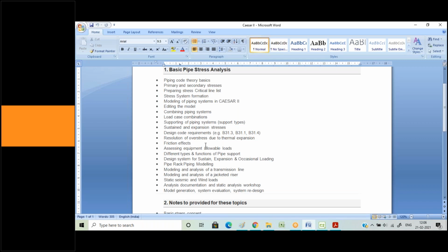Now when you're importing that particular load, if you have messed it up, X goes into Y, Y goes into Z, and Z goes into I don't know what, then that entire analysis comes to zero. So you have to actually understand the axes correctly: what has to be the axial axis of the line, what has to be the tangential axis of the line, and you have to emulate these things well. Okay, so that has to be understood.